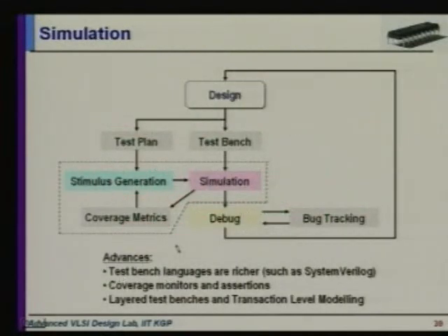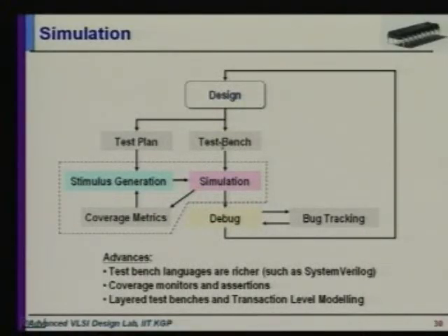This is the typical simulation flow. You are going to learn in this course how to write what is called a test bench. A test bench is a program which includes the design as one of the units and then drives inputs into the design. It generates inputs for the design, and then the simulator simulates the test bench along with the design, checks how the circuit behaves under those inputs, and reports that back to the test bench, and the test bench based on that decides what the next inputs should be.